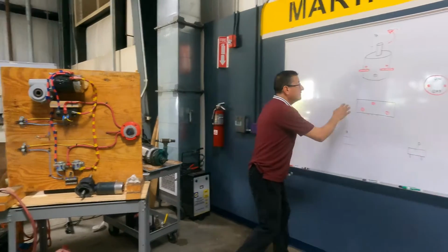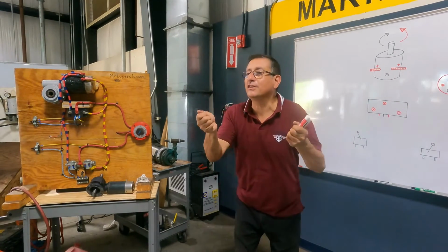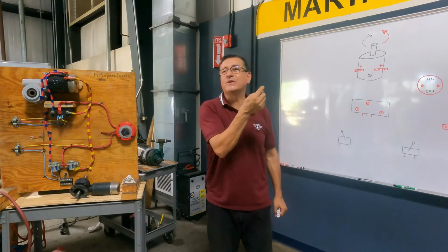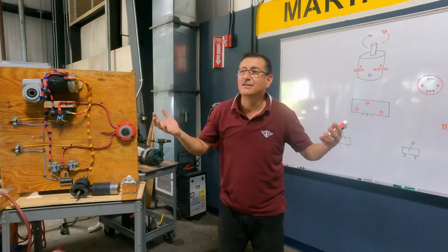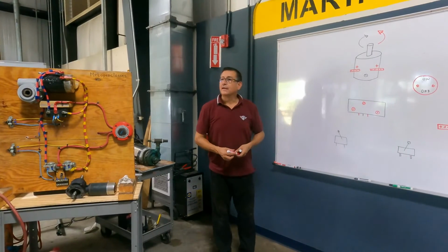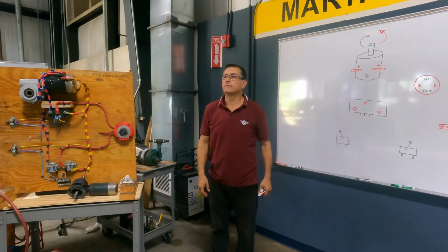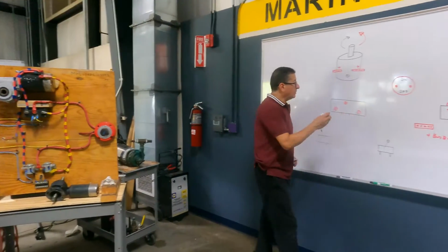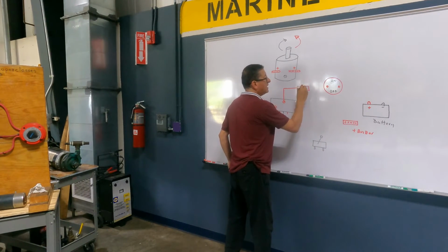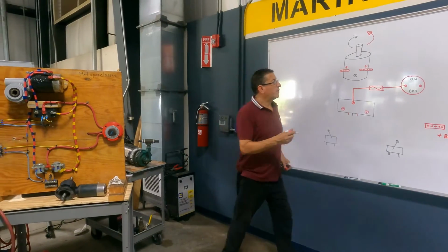Okay, we are going to fit, number one, the solenoid control box. My friend, if you learn this, it is gold in your hands. How many problems, how many situations will you solve in the future with this explanation? Millions. How much money can you make with this explanation, my friends? A lot. All right, I am going to bring power. Where does the power enter the solenoid control box? In the middle. I am going to enter the big current cable, probably with one fuse or overcurrent protector. That's good. And from this one here.